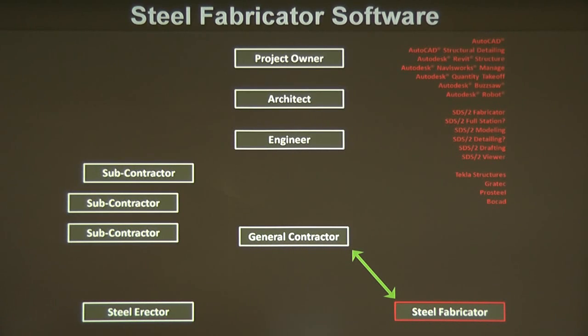In addition to that, the steel fabricator will use CNC information, which is basically a file that tells machines in the shop how long to cut a beam, how many holes it should drill, where the cope goes, and what size the cope is. It's a very, very automated process. And we'll look at a little bit of that too.